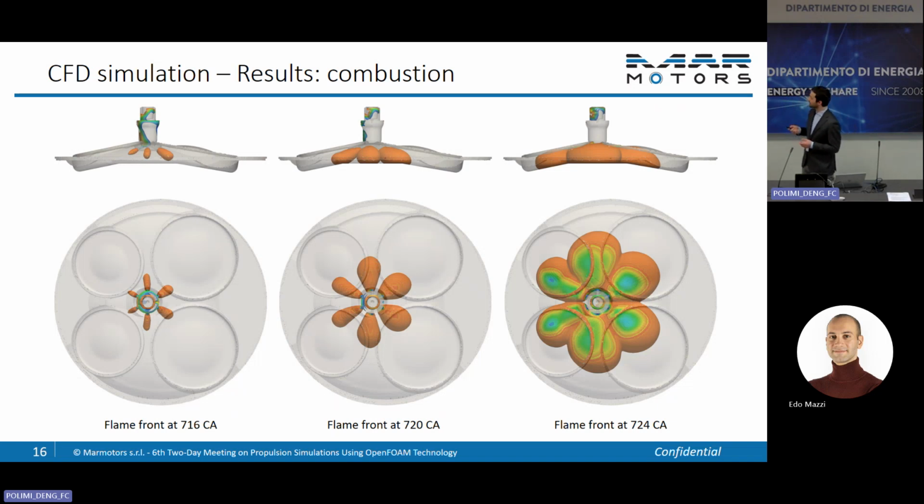But also, thanks to the main tumble inside the cylinder, after the mid part of the combustion, the tumble motion inside the cylinder is disrupting the intake side jets, and so all the jets are arriving to the walls with almost the same penetration.